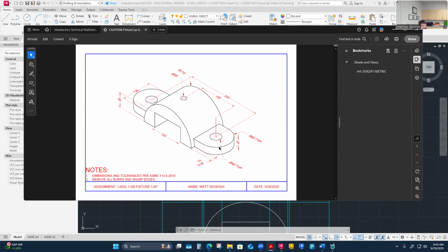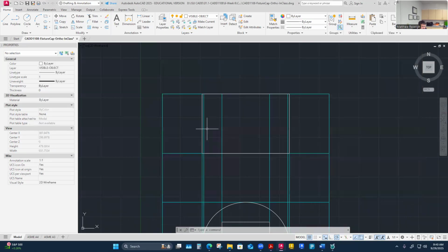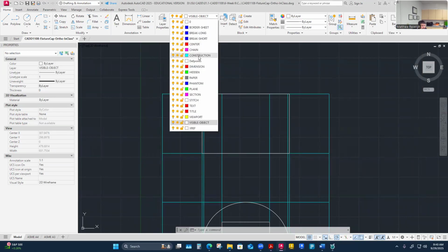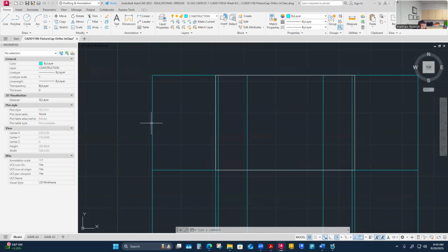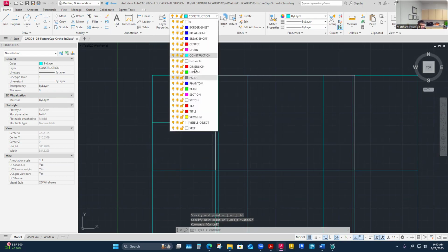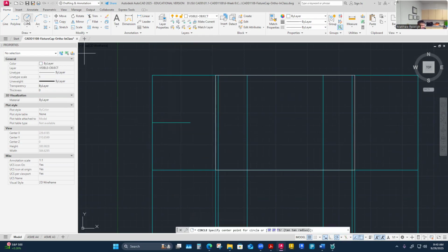It's a little bit assumed here, not for sure, but yes, they are concentric. So 60, I'll come over 60 from the center and put something to construct off of. So maybe I'll do a construction line here from center. I have a midpoint, I think, of this. Yep. So I can cursor over here and just draw this line from the midpoint over 60. That's where the circle is going to be. Those concentric circles. One of them from there has a radius of 60 like that.